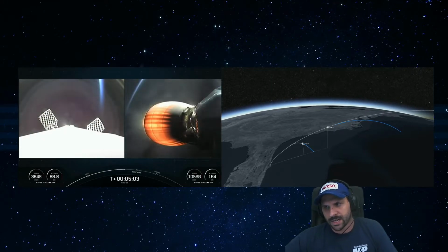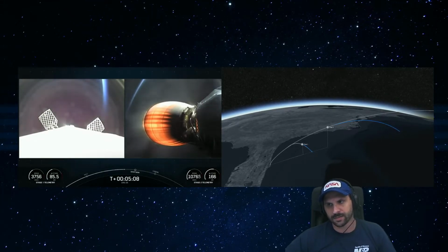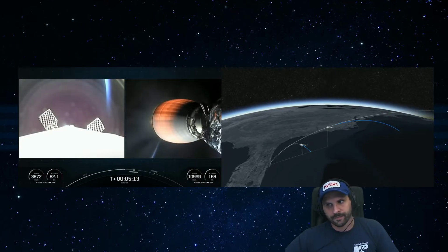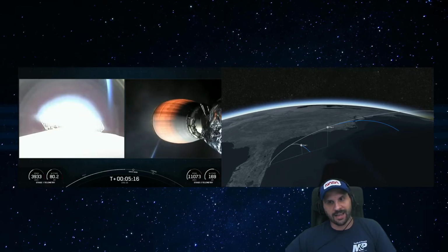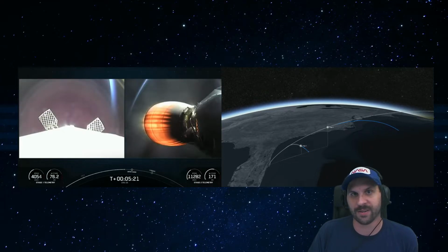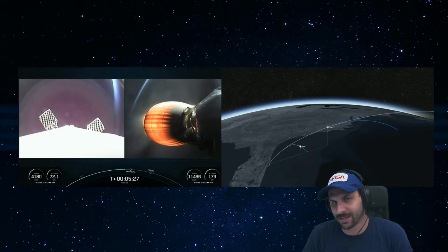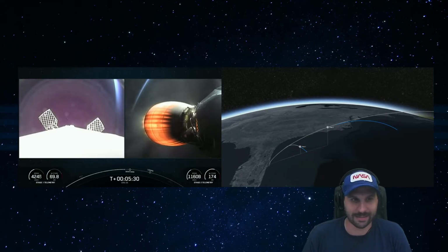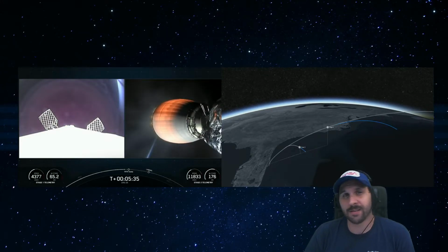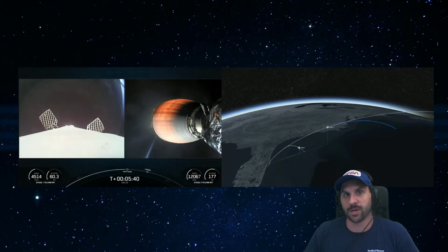Why did they use nitrogen instead of CO2 in the rocket? Lighter. Nitrogen is less mass because it's just nitrogen and not carbon and two oxygens. Plus, nitrogen is inert. I don't think I need to tell you why, the other day when SpaceX was testing Booster 7, why sometimes it might be good to test with inert gases and liquids, so it doesn't pop. Now, don't get me wrong, SpaceX during that test had to test with methane and oxygen because they were testing the starting system. Funny thing is, though, on Starship, SpaceX uses compressed nitrogen to spin the turbopumps to start the engines.